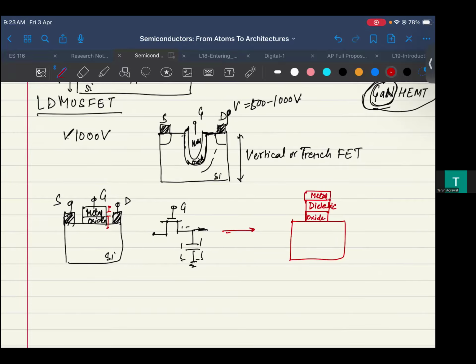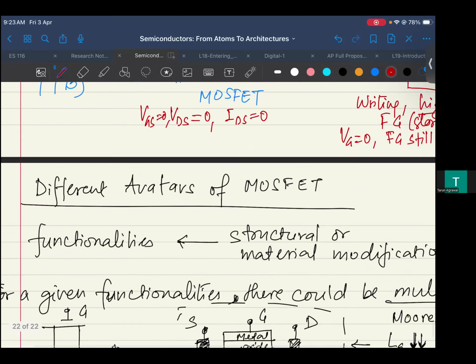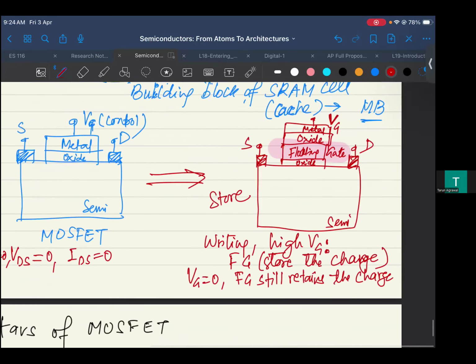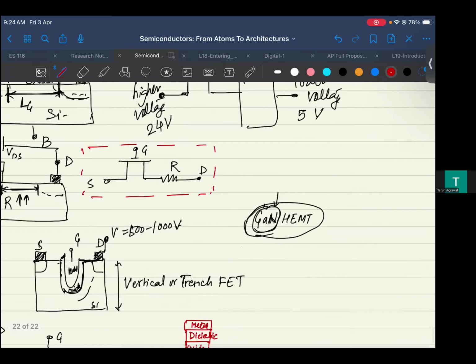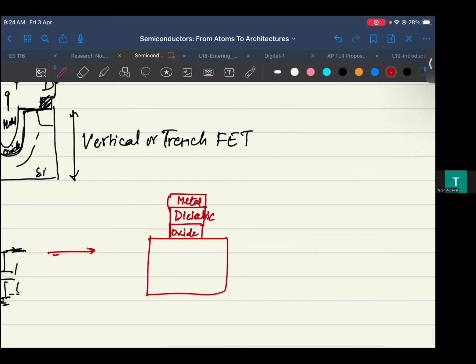So it's very similar to what we did, if you remember, in the FEFET, there we introduced a floating gate which was retaining the charge. Here, to retain the state, we are playing with the dielectric. This dielectric comes with a property because of ferroelectricity, that's a ferroelectric dielectric.